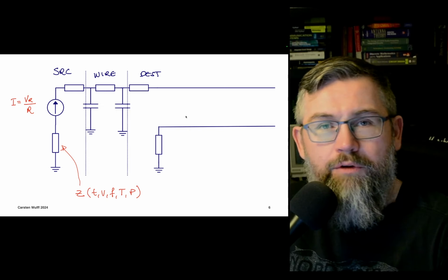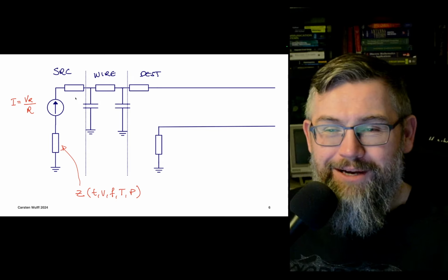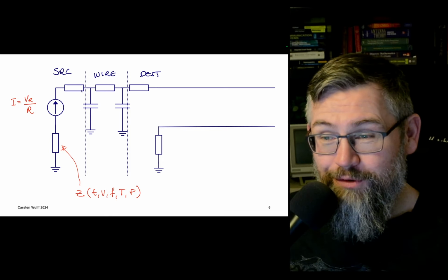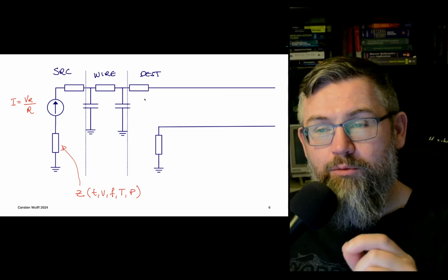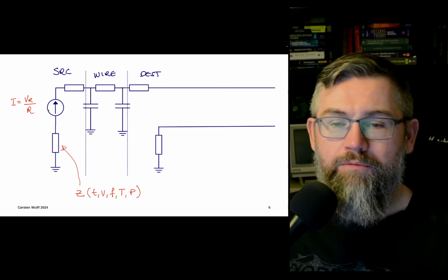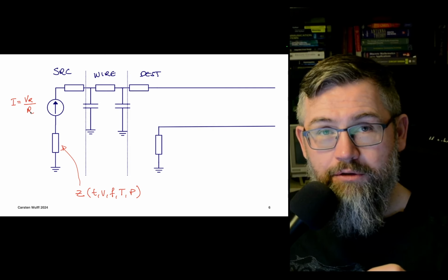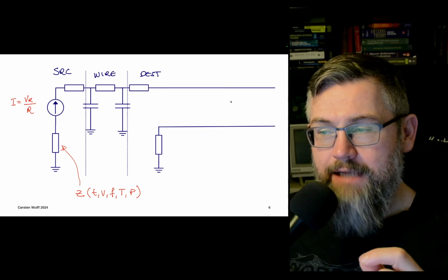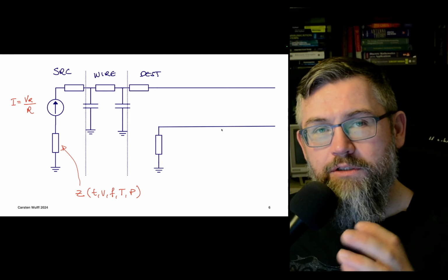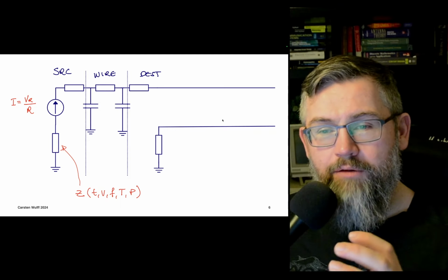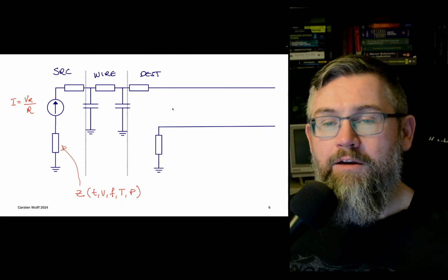Because currents flow in a loop. We know that as long as it doesn't disappear, as long as there's only one loop, then we know that the current will be the same. So, for example, if I have a voltage divided by a resistor, and I use exactly the same resistor on the other side, now I know my voltage is the same. My reference voltage has been copied all across the chip, and I'm happy.